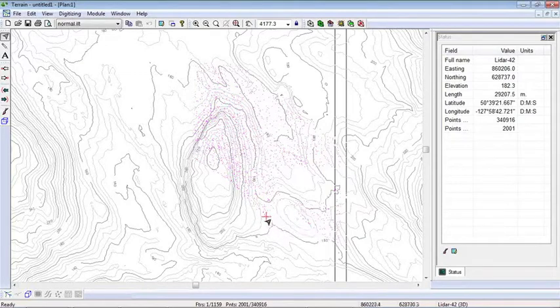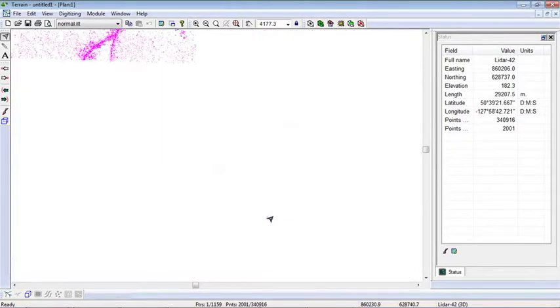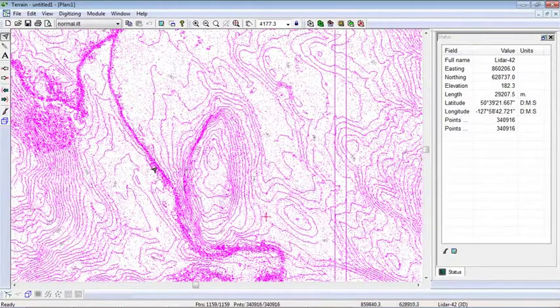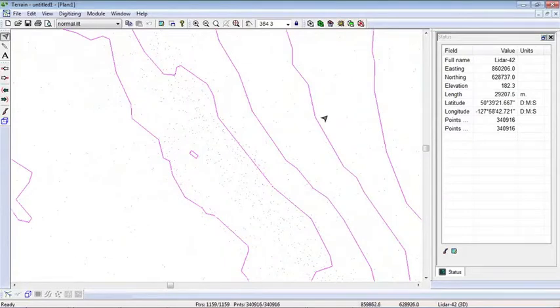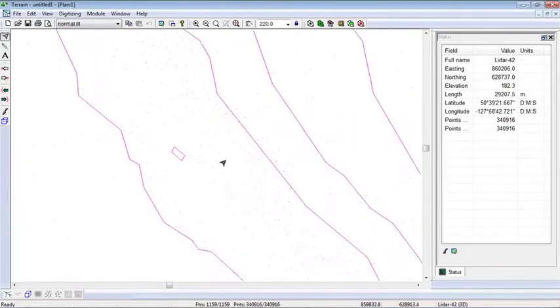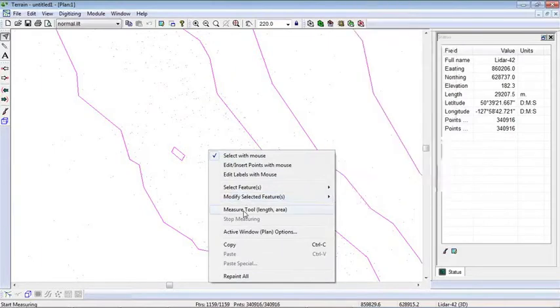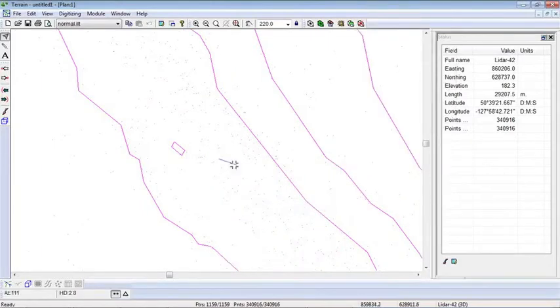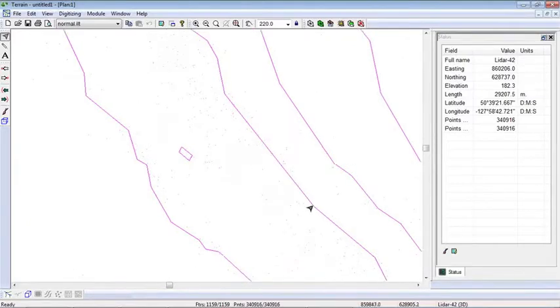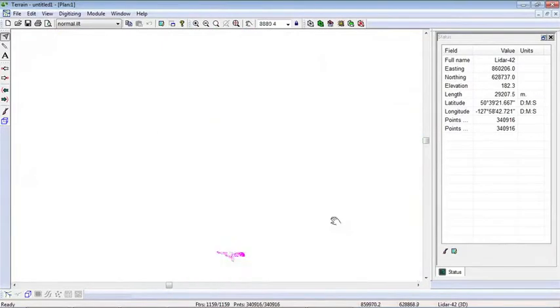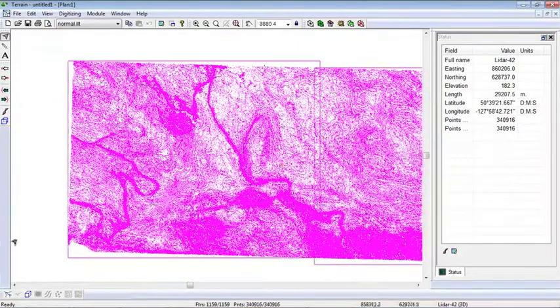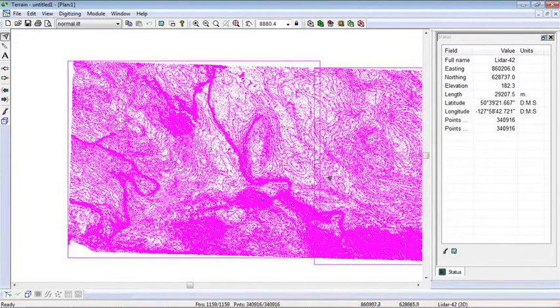And then let's just select all again, Control A. If we look near the road where the data is open, by the way, that 20 meters, of course, is for the thinned data, 1 in 10 points. We'll look again when we get a higher resolution read. Here in the road area, the distance between points is quite small. So between that point and that point, for example, is only 3 meters. The person who lent us this data said that it was roughly 1 point per meter on average, but you can see it's quite varied.